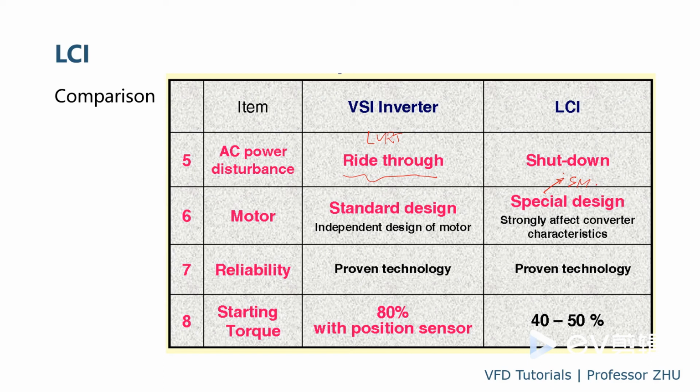And also, when you drive the motor with the VSI, typically during running, when you adjust the speed, the power factor of the motor is always kept at 1. So that means the current of the motor will be minimum, with low loss, and high efficiency on the motor, and also high efficiency on the drive, and also for sizing the current of the drive, because the PF is 1, so the current is minimized.